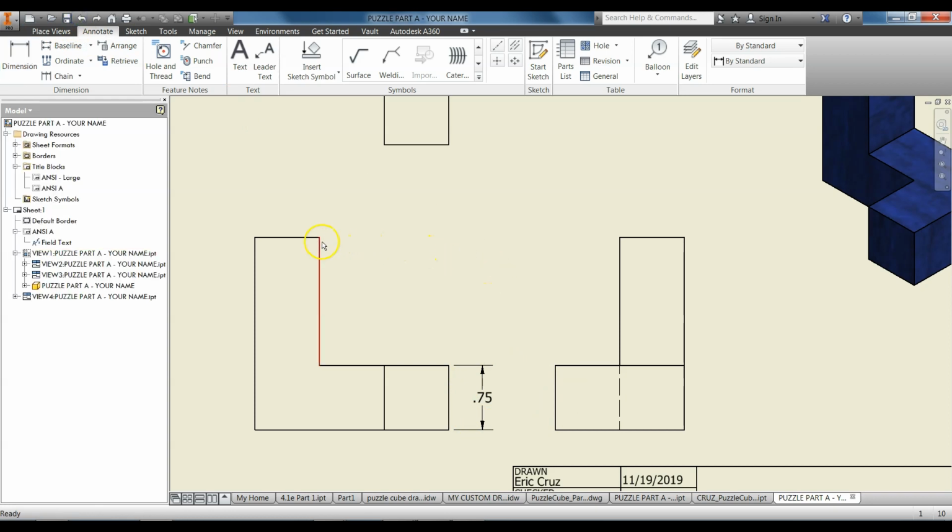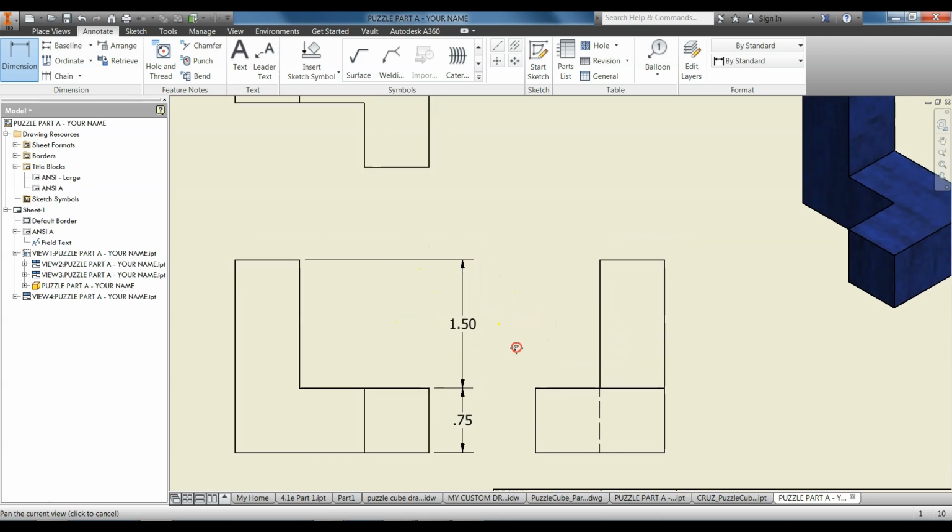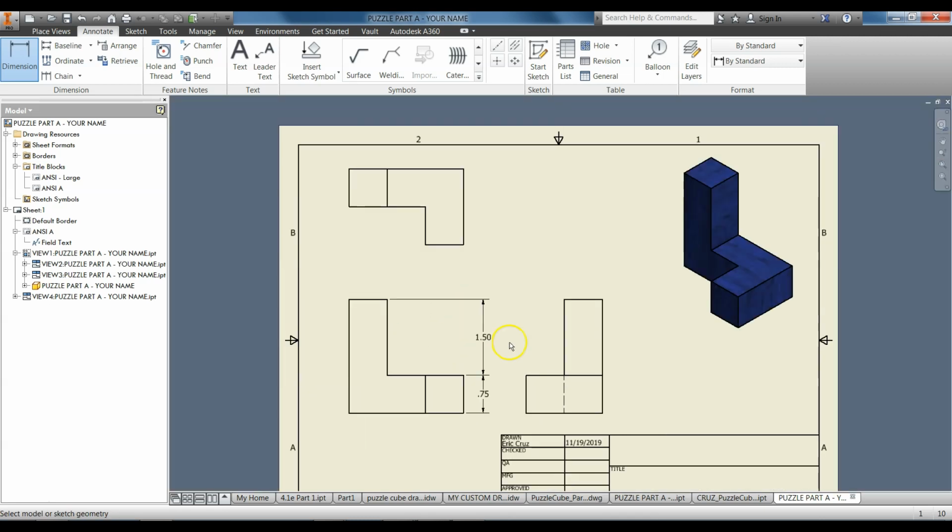And then I'm going to click on the corner. So let me click on dimension again. I want the corner of this one, so that green little dot, and then the corner of this one, because what will happen is these dimension lines should not touch the actual part, and it'll give me the length between here and here, which is good. Okay.